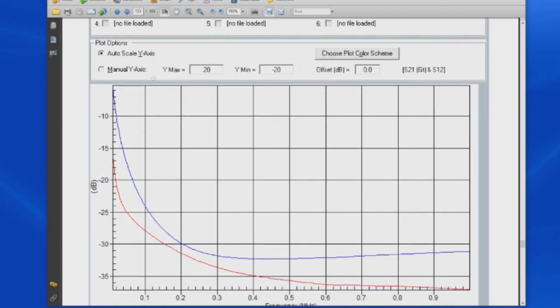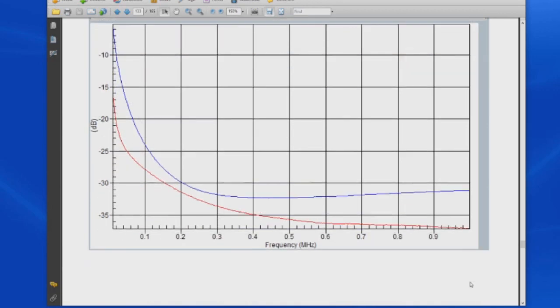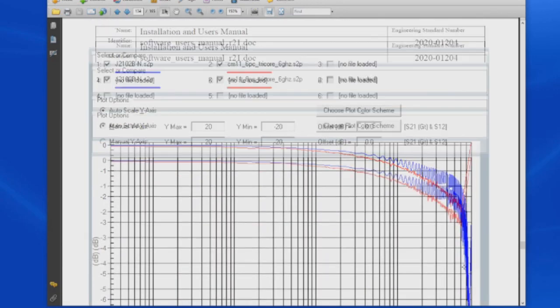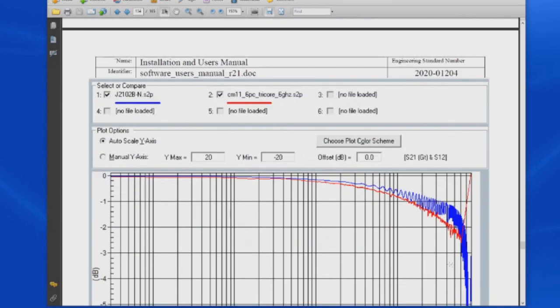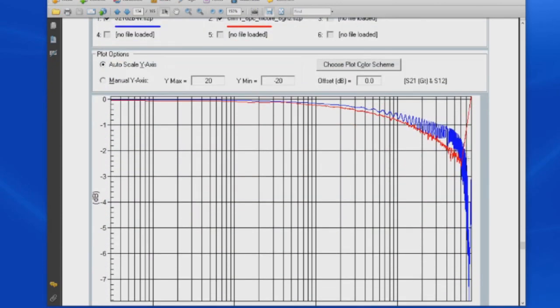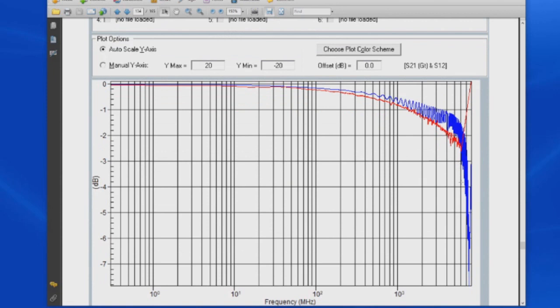And we can see now the common mode performance for this transformer is better than the Pico test transformer all the way up to 1 megahertz. And if we look at the return loss now, we can see it's much, much better. So a couple of things. Brian had collected data all the way up to 8 gigahertz, and I'm showing that here. And of course, I'm not able to run up quite that high. I'm collecting data all the way up to 6 gigahertz. And you can see how it flings off. This is just how AppCAD works when it reaches the end.